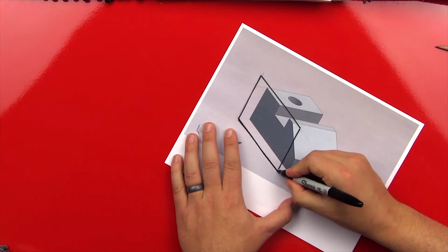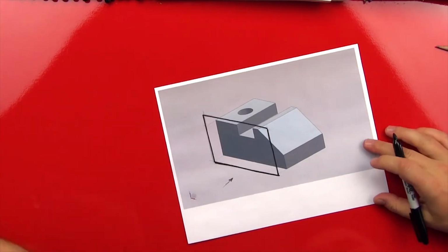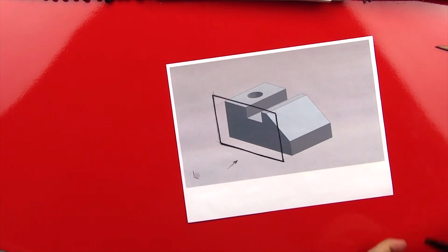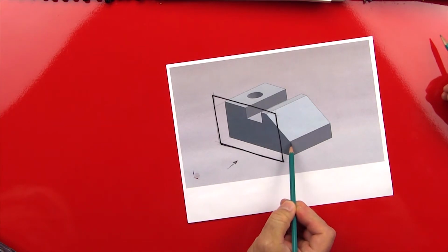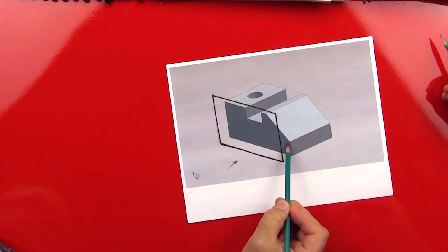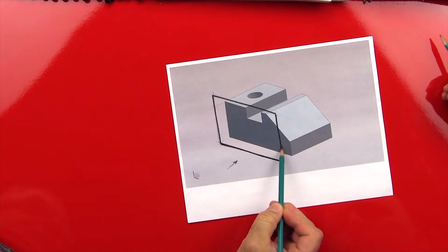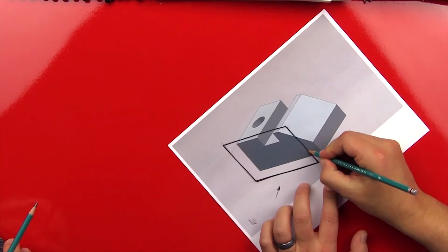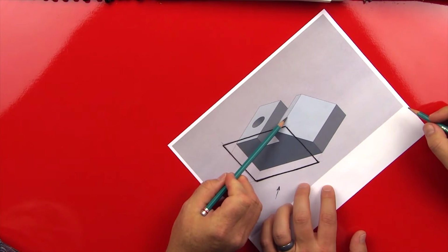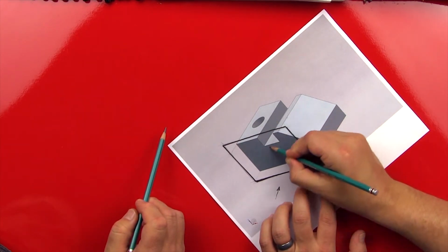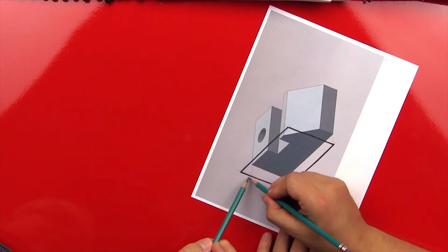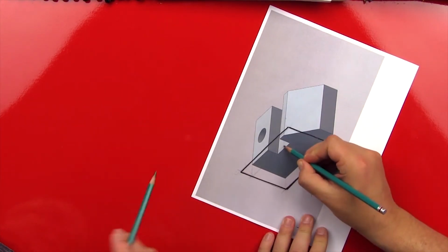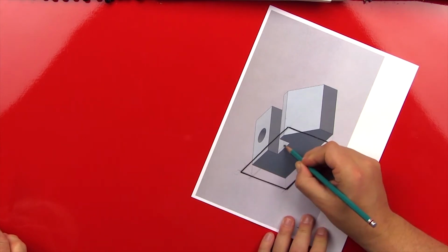So that represents this plane that we're going to call the front view, or the front orthographic view. Now what you do is you project intersection points. So we can just project this line out to where it intersects and put a dot there. We can do that to this line. That's got to use your imagination, huh? Right, but you can use approximately the same depth that you're off.